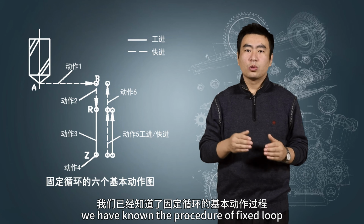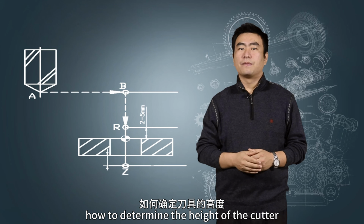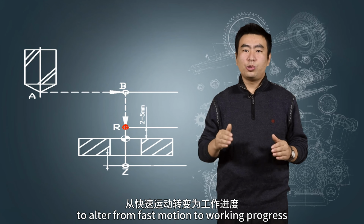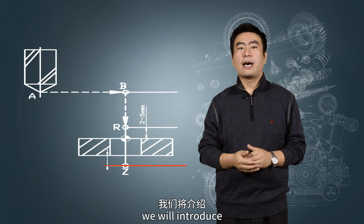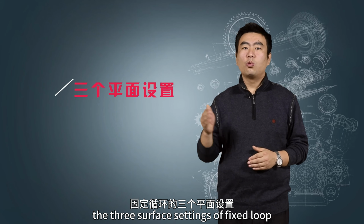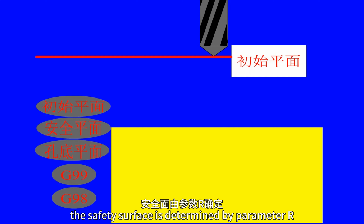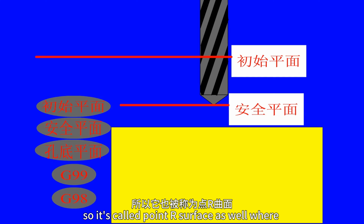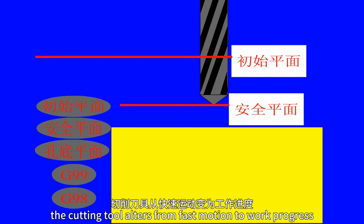We have known the procedure of the fixed loop. So, when processing, how do we determine the height of the cutter, which will determine the position where the cutting tool alters from fast motion to working feed, and how do we guarantee the depth of the hole? Next, we will introduce the 3 surface settings of the fixed loop. Among them, the initial surface is determined by G00 before the loop starts. The safety surface is determined by parameter R in the instruction. So it's called the point R surface as well, where the cutting tool alters from fast motion to working feed.